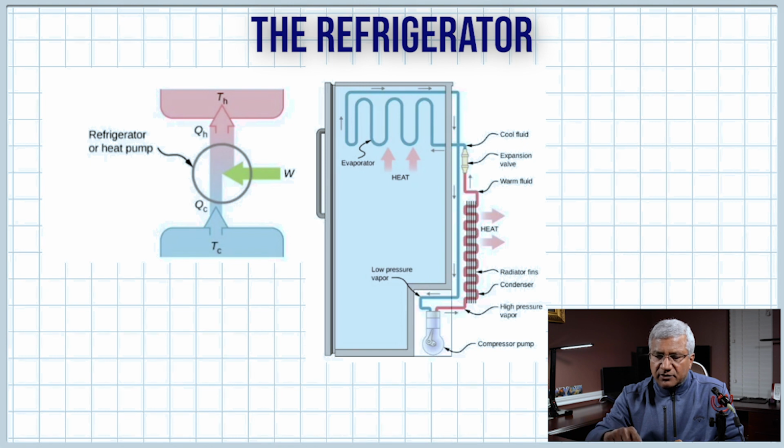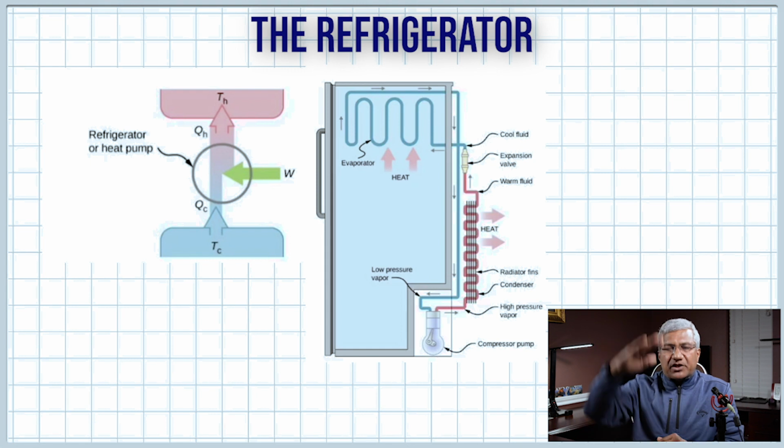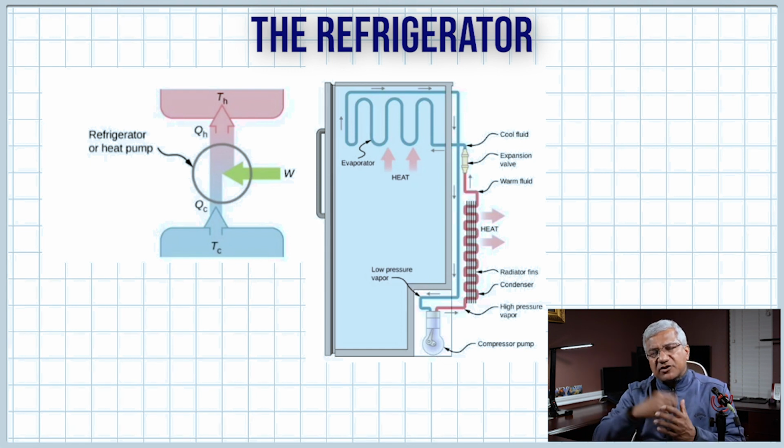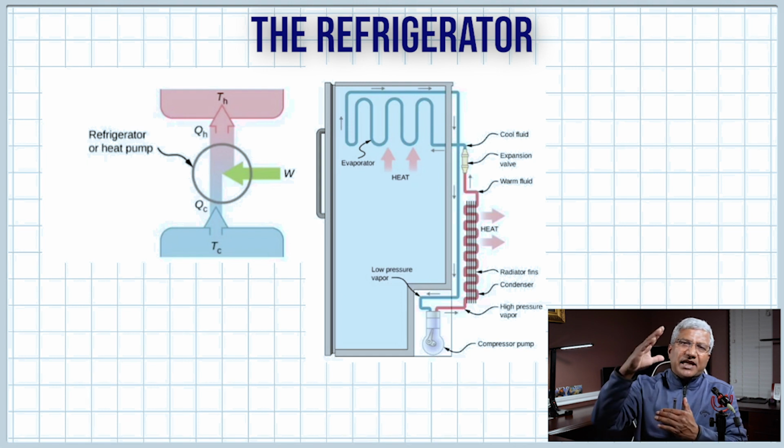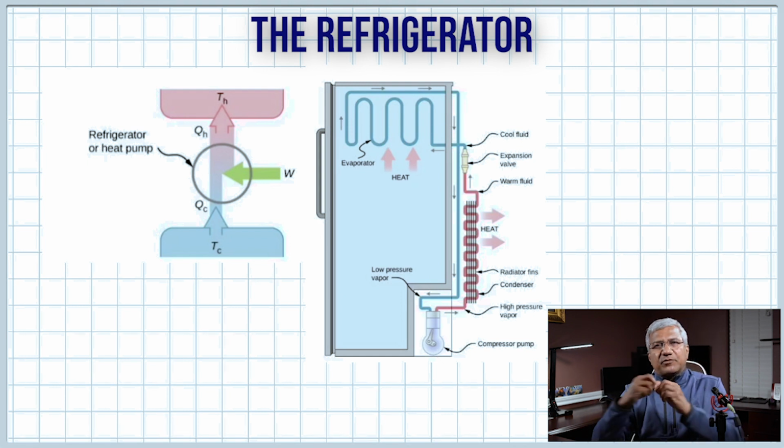And then the gas returns to the compressor while the piston is going down. See that? So as the piston goes up and down, this cycle is repeated. So each time the liquid changes into the gas, it takes its latent heat from the food in the freezer, so the food gets cooler after each cycle. So that's the functioning of a refrigerator.